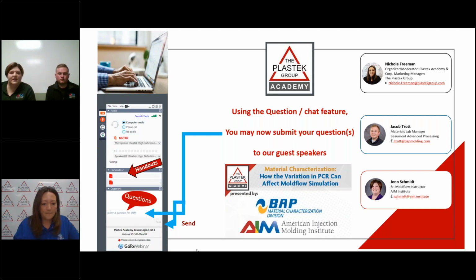So in the simulation program, there's a studies task pane, and there's tiny little icons that give me a very quick reference, whether it's gold, silver, or bronze. But I think the better way is to go into the material details, which is some of the pages Jake had shown, and then you can click in that material data indicators, and it will tell you, his example was gold, gold, gold. But it would tell you the different classifications. In warpage, the gold is somewhat mesh dependent. So I always tell people gold may not be enough depending on how it got to be gold and what mesh type you're using. So I think it's good for the analyst to go in and dig into that a little bit more.